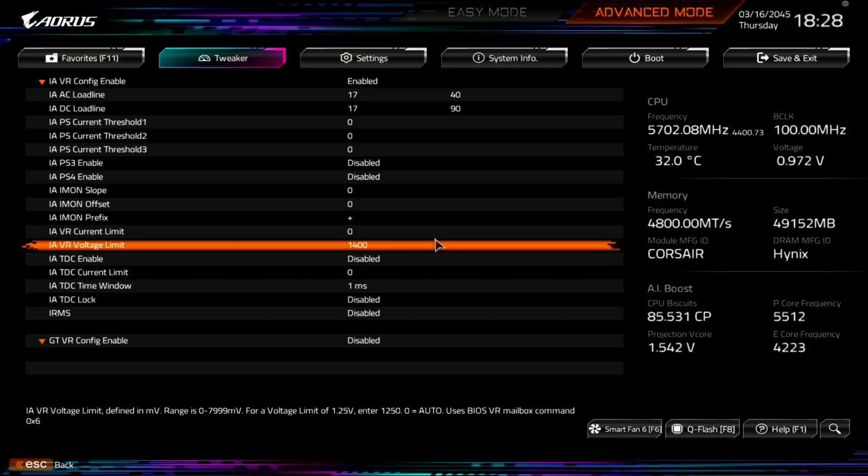Right? Especially because the overshoot is actually outside of the control of the voltage regulator. The reason you get that overshoot is because the voltage controller literally cannot react quickly enough to the load transient that it's going through. So when the CPU goes from very high load to low load, the change in impedance of the CPU is so fast that the voltage regulator doesn't have time to react.